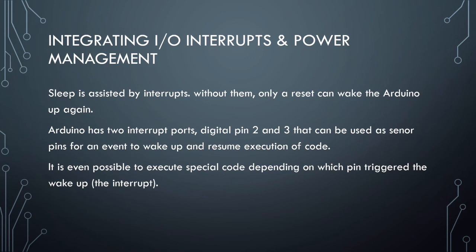An Arduino board, we're using a LaunchPad, but an Arduino is really similar. It has two interrupt ports, digital pin 2 and 3, that can be used as sensor pins to wake up and restart the code where it left off. A reset starts over from the beginning. If we do a sleep with an interrupt, it will just pick up back where it left off.